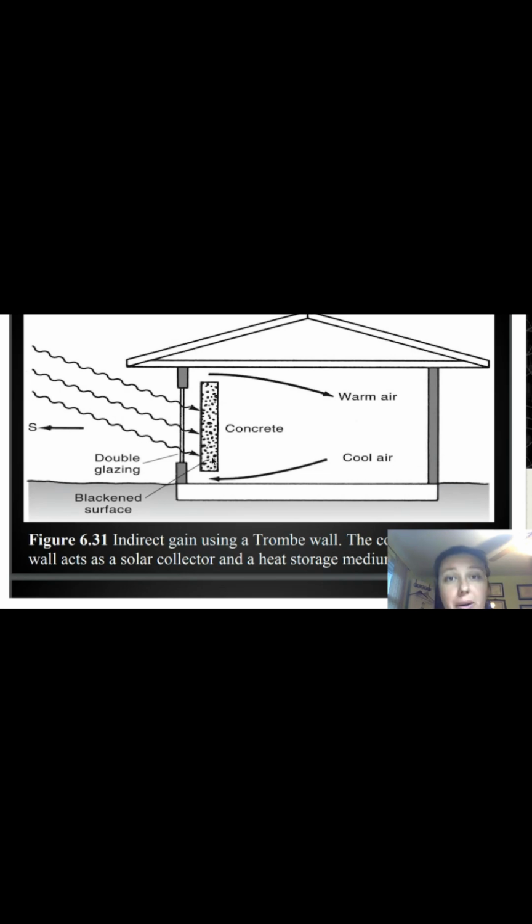I mean, for the most part, somebody closes the blinds and they don't get opened again for months and months and months. So, take advantage of the system that's there, and you can do something very sustainable with the capacity that's present. So here's some examples of Trombe walls. Once again, it's not blocking the window itself, but it's very close to the window. And so here's some Trombe walls, right?